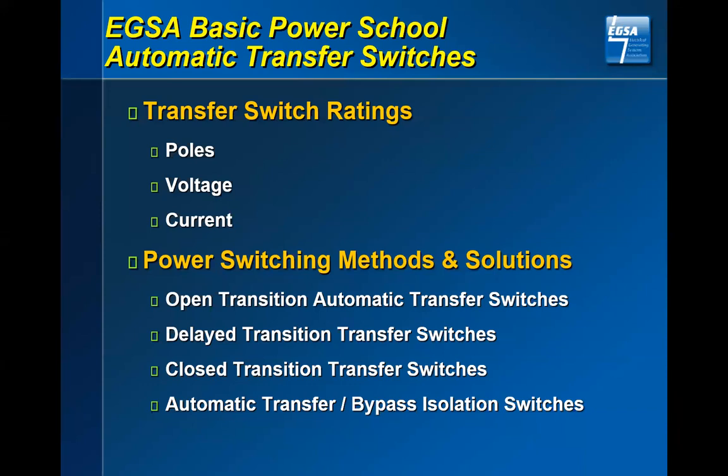It is very important to know the voltage that we're looking at. Many products, and we're going to touch on one of the slides, is what's referred to as a safety switch. It was sort of used as a manual transfer switch before. It is still popular doing that way, but all of those products are rated for 600 volt. Anywhere from 120 to 600 volt is that class of product. In sales, we'll have people call us and tell us that they want a 600 volt transfer switch. Well, typically in the United States, we do not use 600. We use 480 volt. So you need to know the application voltage that you're using.